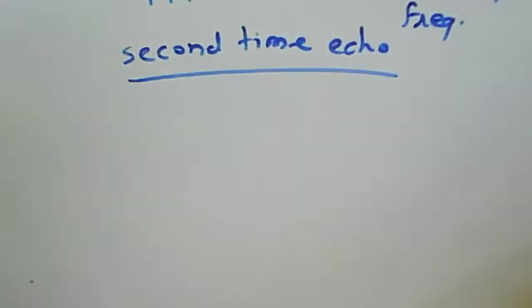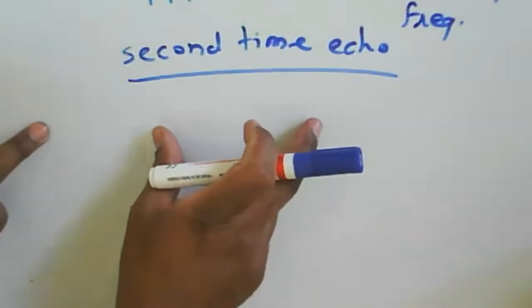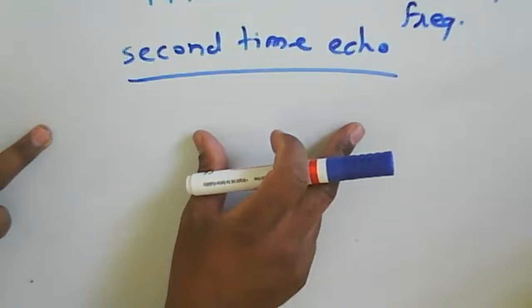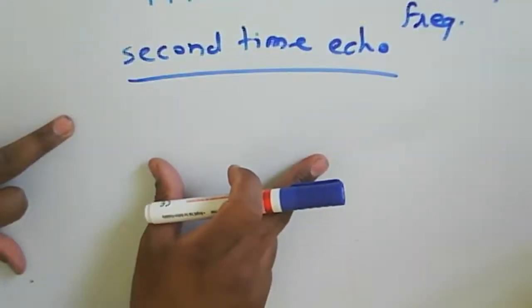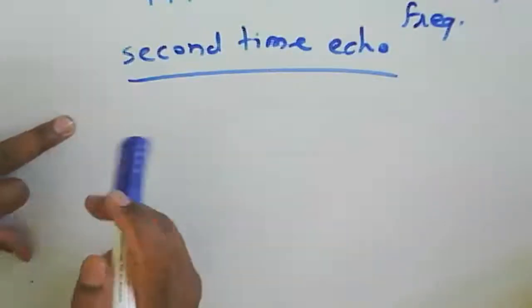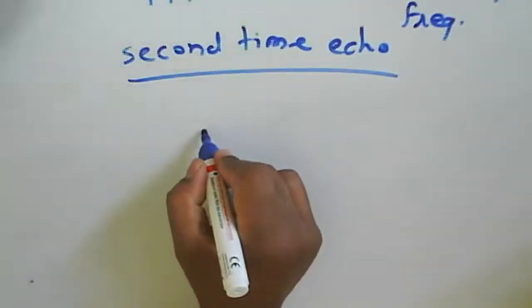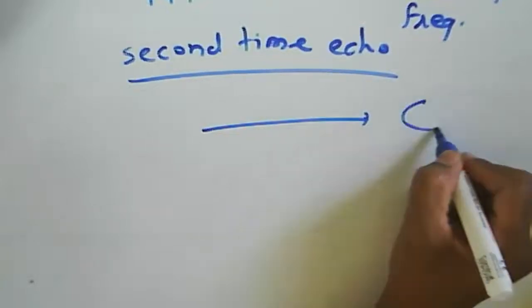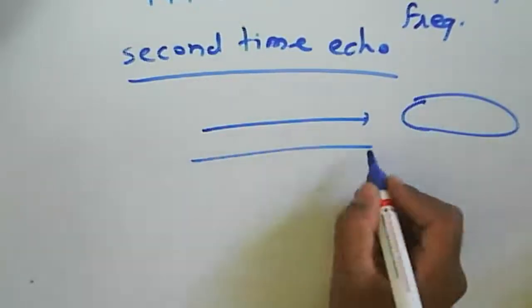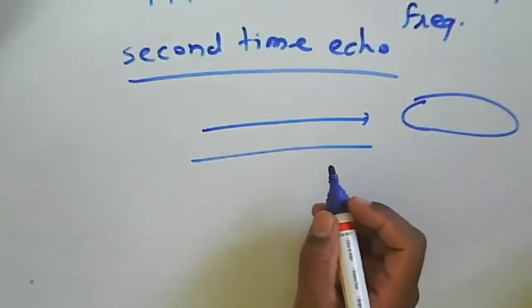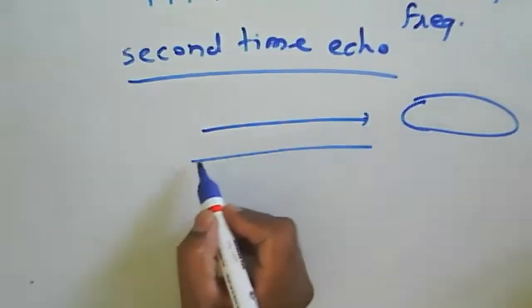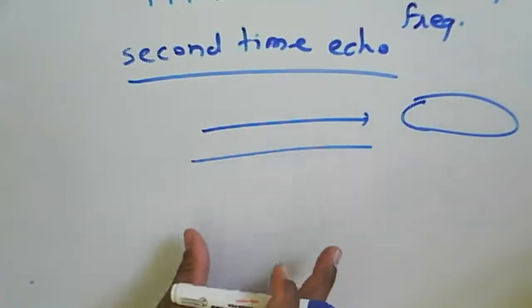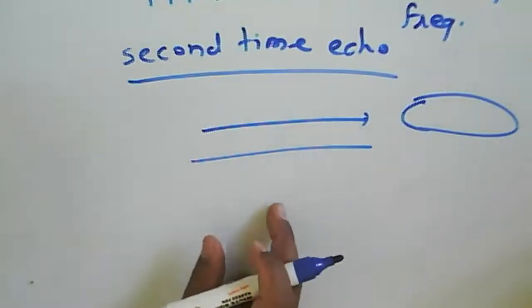Because second time around echoes will occur at the same frequencies from the same range of a pulse, or we can say that we are sending the signal to the given target with two different pulse repetition frequency signals. Then in that case, for the given particular range, it will produce uncancelled residues there.